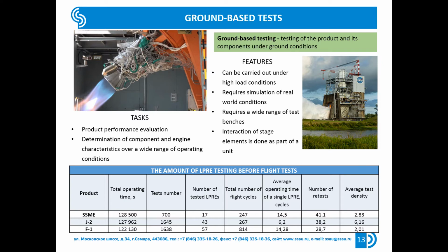Since the operating mode and performance of the LPRE can also be significantly affected by the temperature of the fuel components and its design, in some cases, thermo-vacuum tests are carried out on specially designed test benches for this purpose. The combined operation of the propulsion system and the LPRE is verified by comprehensive ground tests as part of the rocket stage. Intensive ground testing of the LPRE and extensive use of real-world simulation facilities significantly reduce the amount of expensive flight testing.